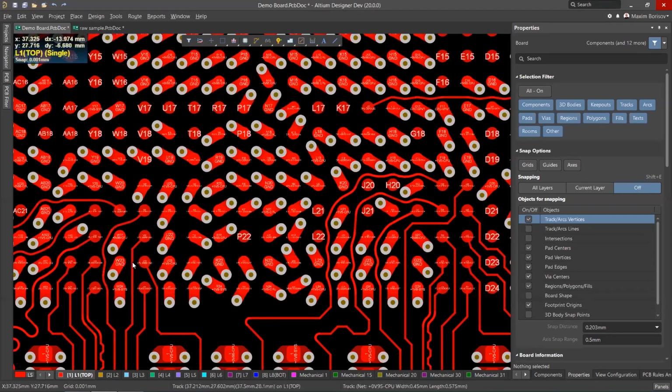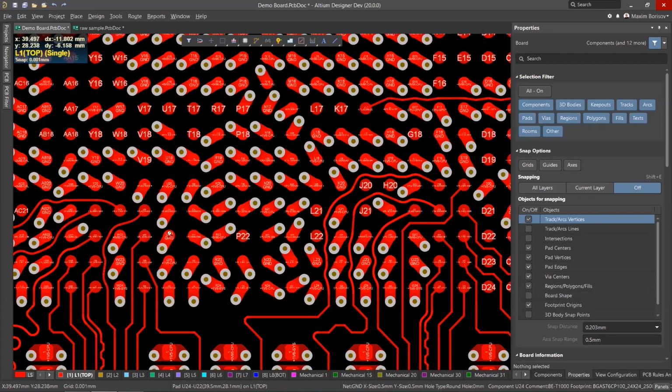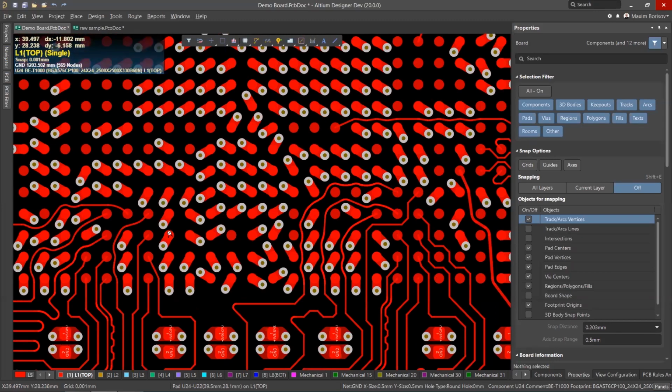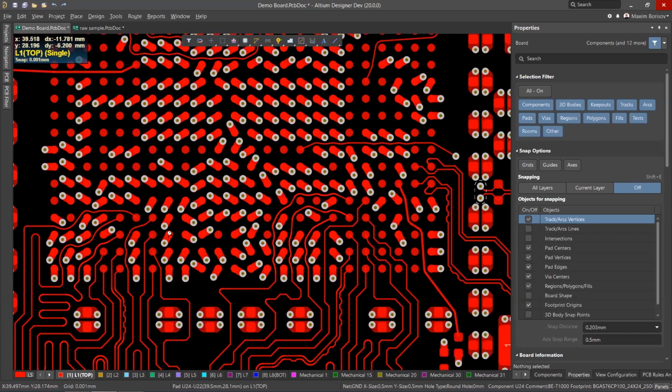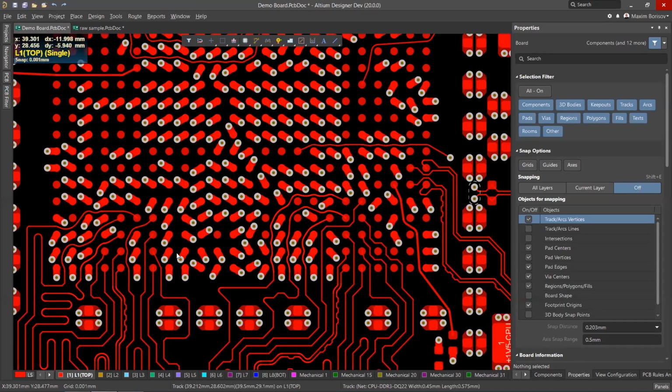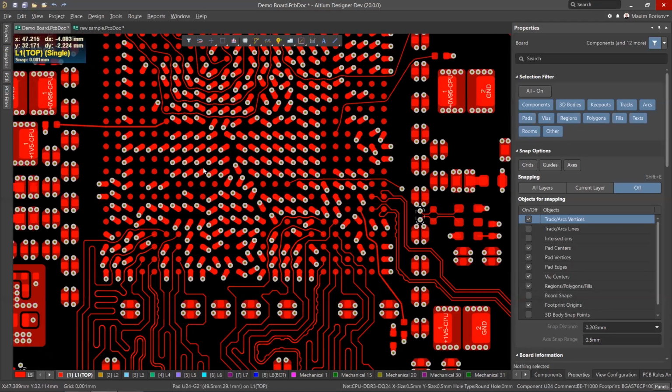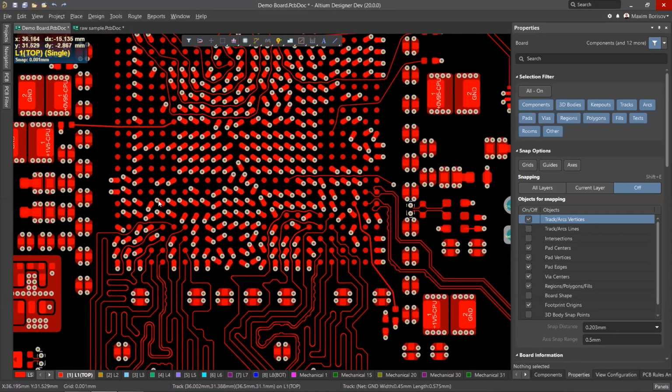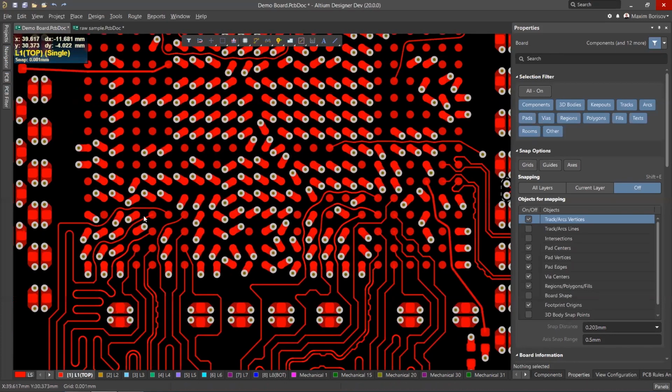Even with extremely crowded environment, you can easily retain the good power integrity, at the same time keeping all decoupling capacitors and the target integrated circuit on the top layer, because as it was mentioned previously, I managed to utilize inner layers better.